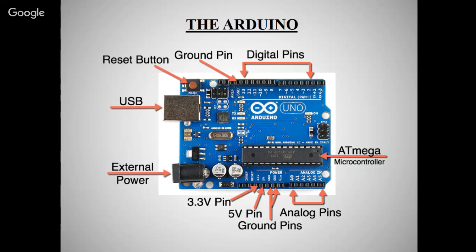By this pin you can also control other solid state devices, transistors, and MOSFETs, and then control the speed of the motors. There is also one LED connected to pin 13, an inbuilt LED, just near the 13 pin.